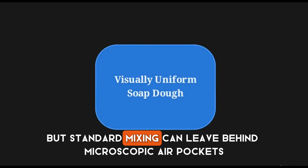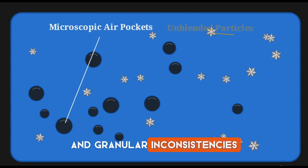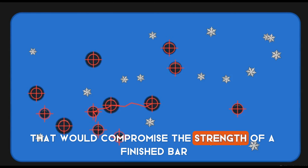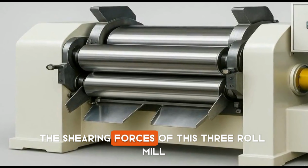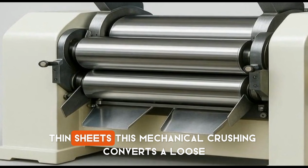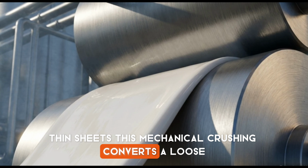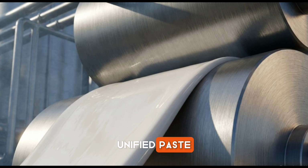But standard mixing can leave behind microscopic air pockets and granular inconsistencies that would compromise the strength of a finished bar. The soap is fed through massive steel cylinders. The shearing forces of this three-roll mill crush the material into paper-thin sheets. This mechanical crushing converts a loose, dusty mixture into a smooth, unified paste.